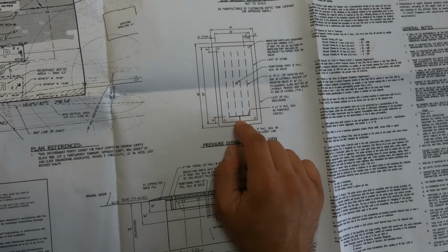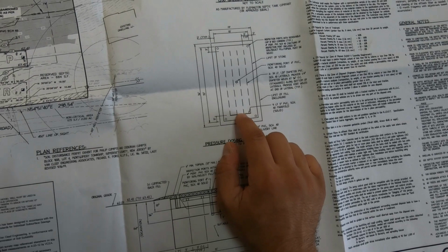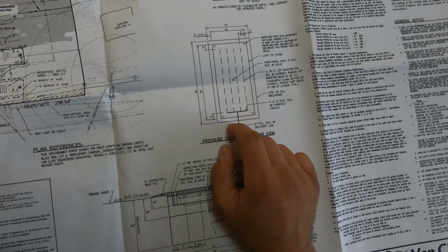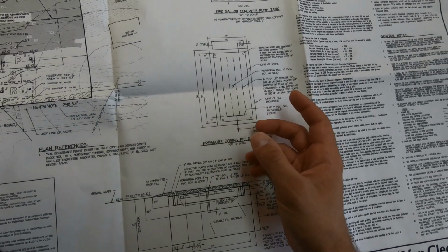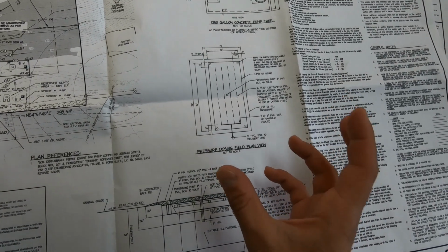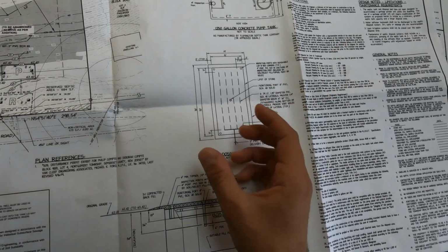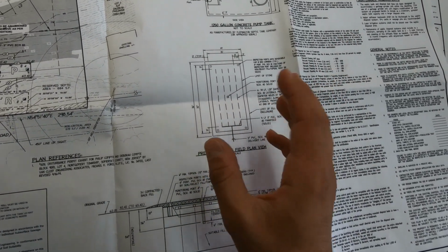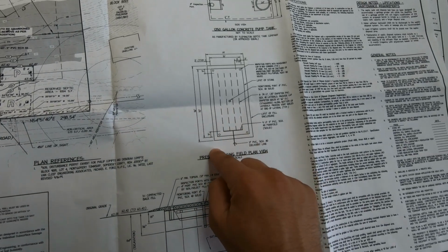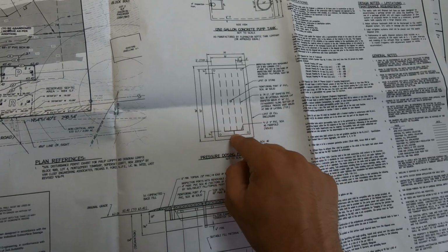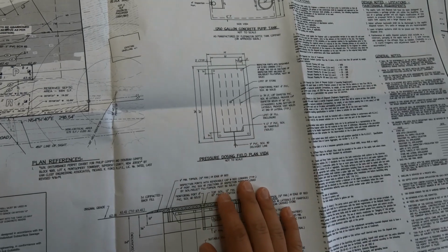Sometimes we do it with a garden hose. Sometimes you just get a couple buckets of water, you dump it in and just make sure. And sometimes they install speed levelers, which are just small little pieces that fit into the pipe, and you can basically turn them so that all of the openings are equal, and so the pipes are getting equal distribution.